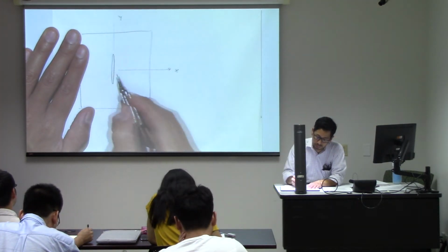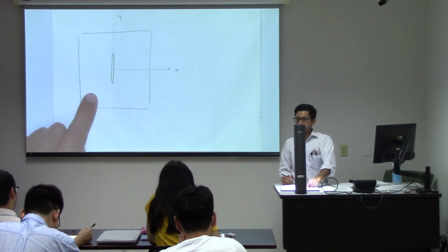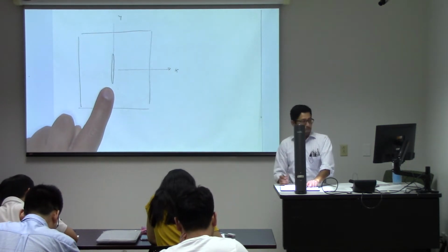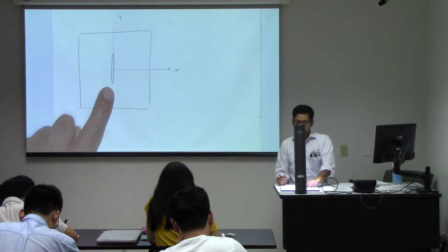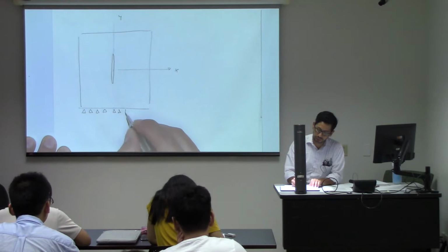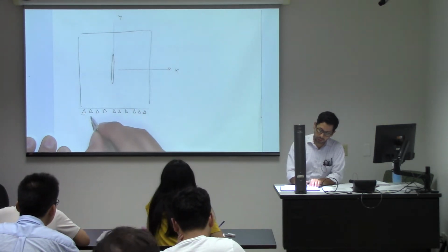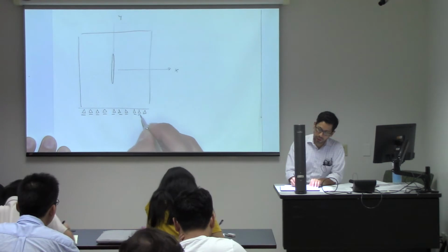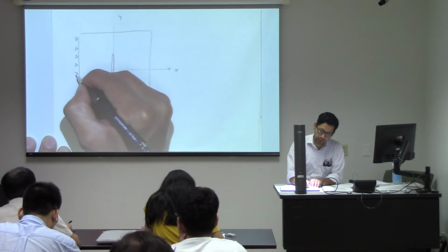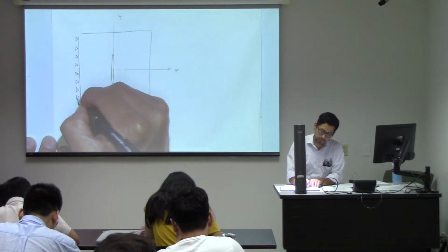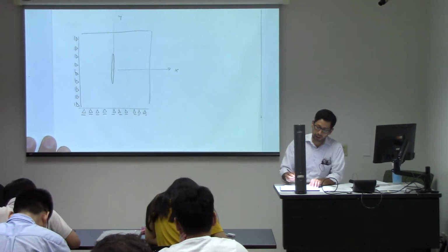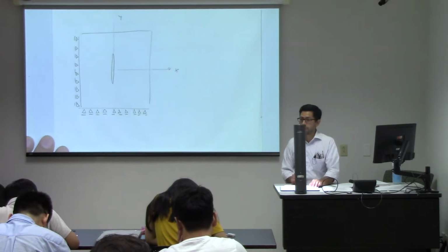Something like this. And you could apply pressure inside this elliptical fracture, and tell this boundary not to move in Y direction, and this other boundary not to move in that other direction, and to have a pressure inside here, and that would be the end of the problem.